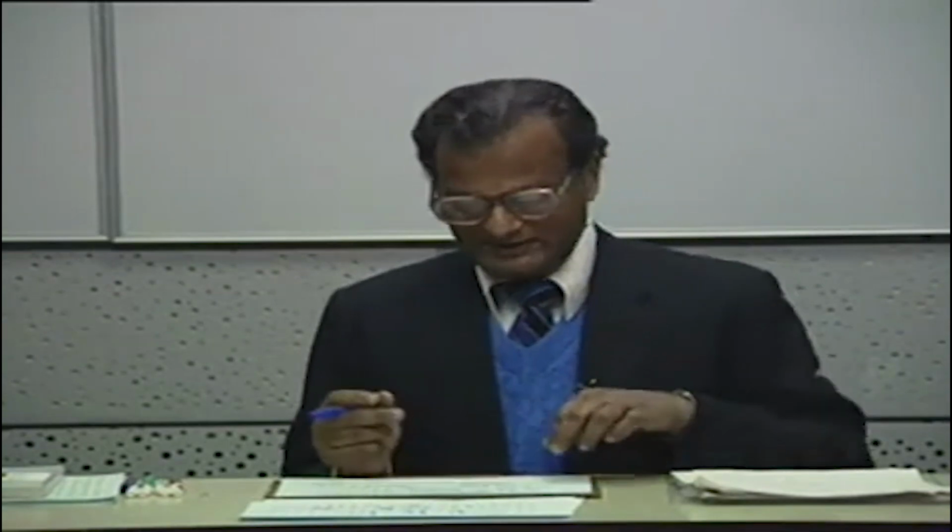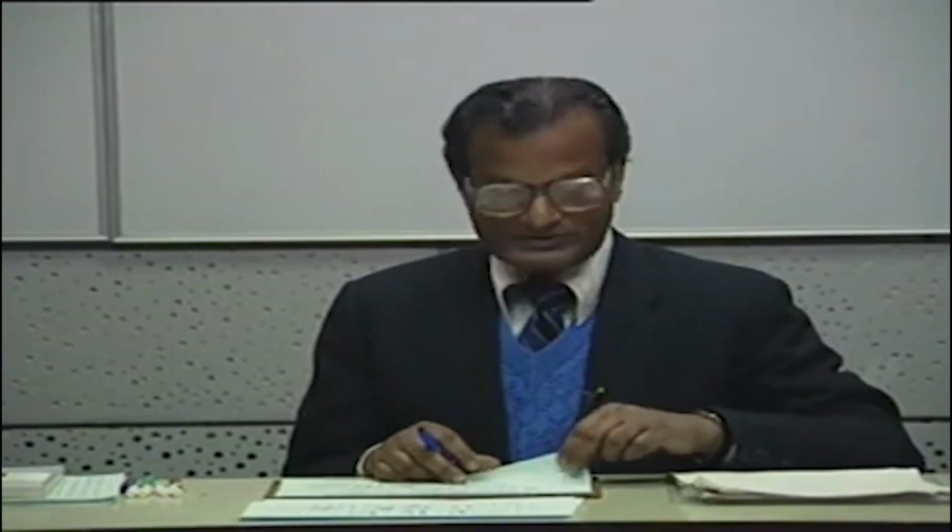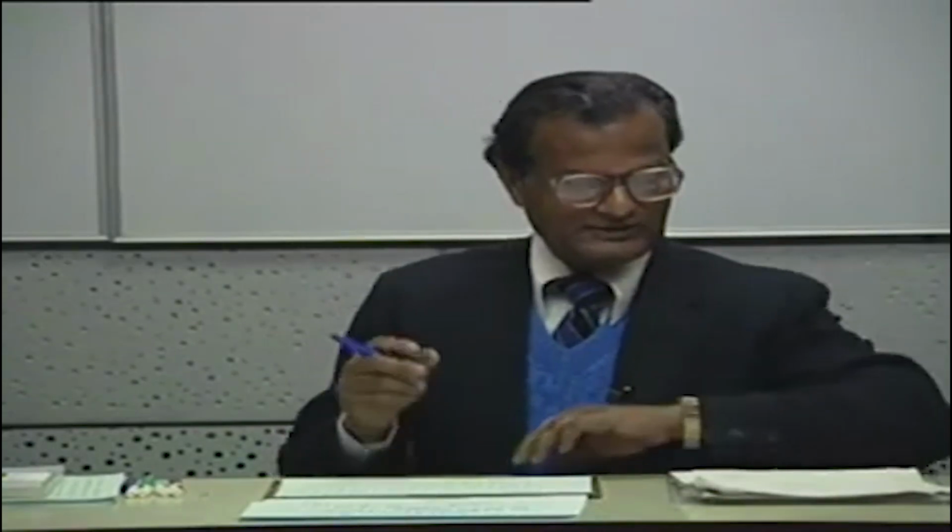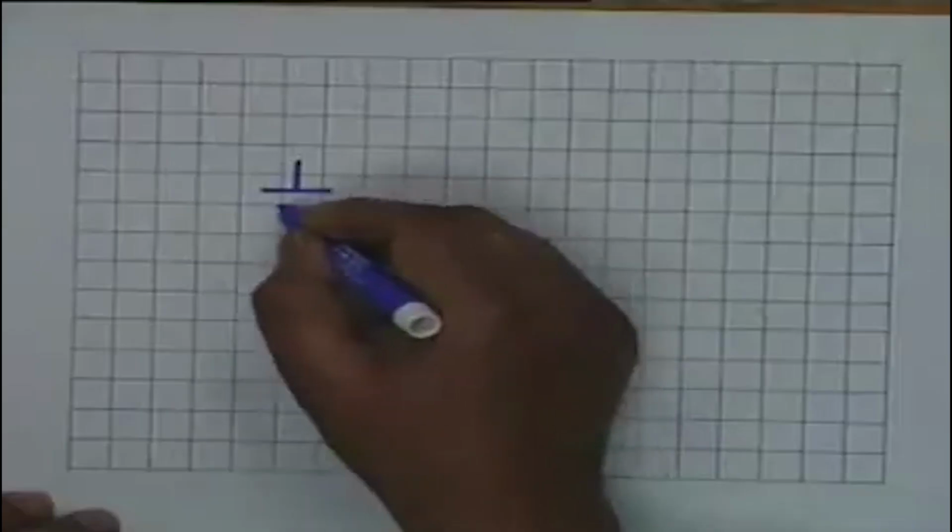Let's concentrate on superposition. Superposition also allows you to solve or analyze a network without writing elaborate equations or without solving simultaneous equations. As you shall see, superposition along with source transformation sometimes can solve very complicated networks without writing a single loop equation or node equation and so on. So these are tricks of the trade, and we shall illustrate superposition by means of the same example that we have been taking again and again.